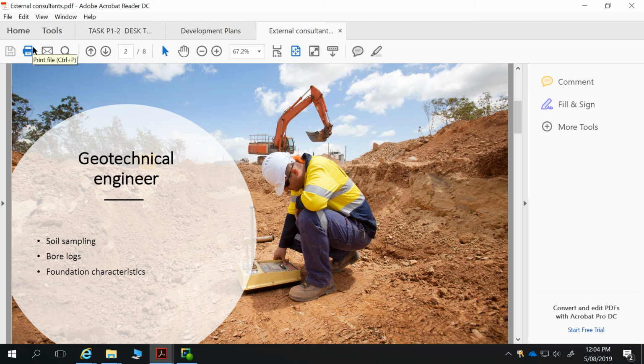If ever you go down to the beach and some of the southern beaches, you look at those cliffs there, you see these horizons of soil, and you'll see that sometimes they're really thin, and then other times that same horizon of soil is quite fat. That's what happens underground. The geotechnical engineers are going to want to know that, because that tells us what footings we can do. And also, it's not just about going, okay, this is the reactivity of the soil, this is how thick our footings are.